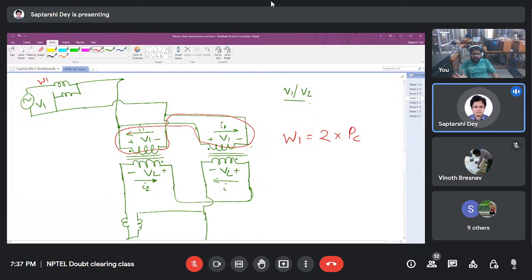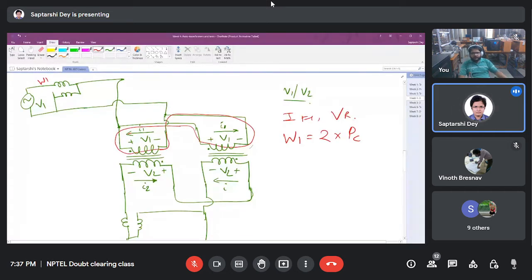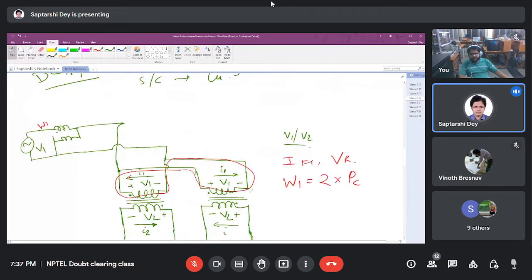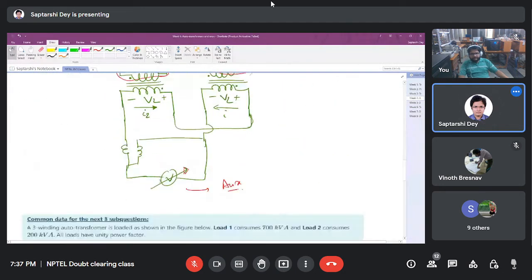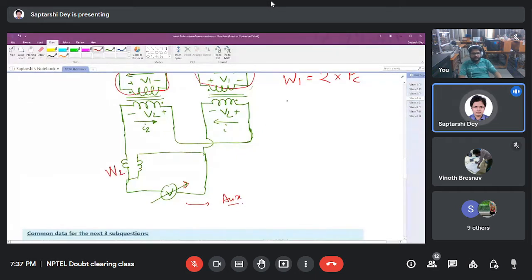So we are not drawing any current from the supply. The load current, we are not drawing from the supply, but still the transformers are operating at full load current and rated voltage. But they are drawing what? They are drawing only the losses. So this wattmeter W1 is supplying the core loss. After connecting all these things, this current did not change. We have proven, so the short circuit power must be coming from 2. Short circuit power means the copper loss.